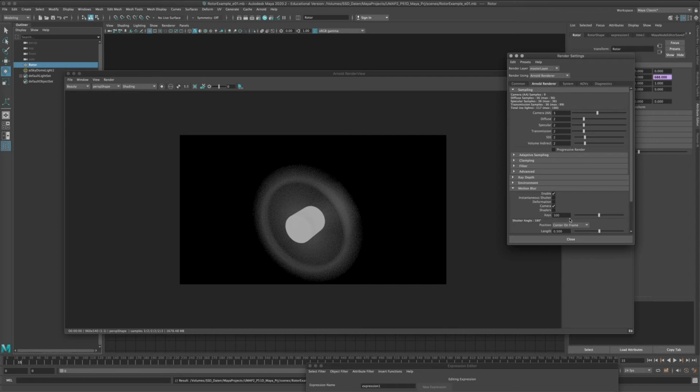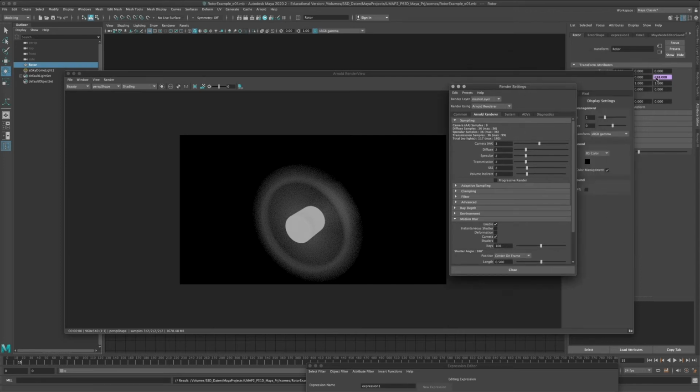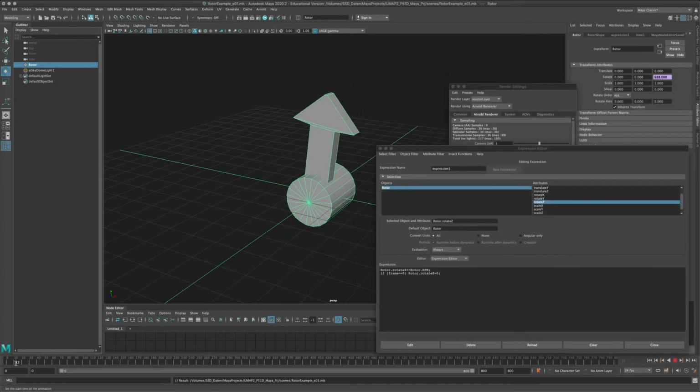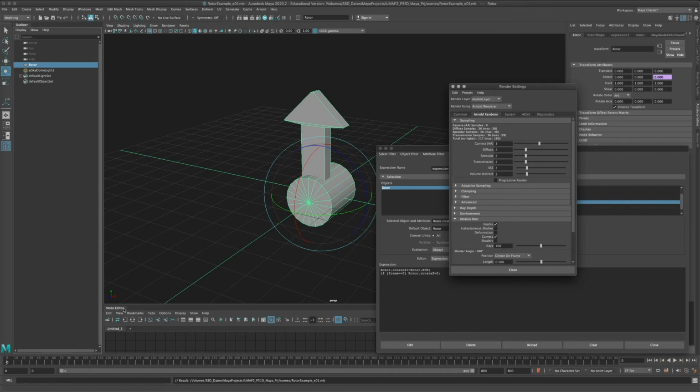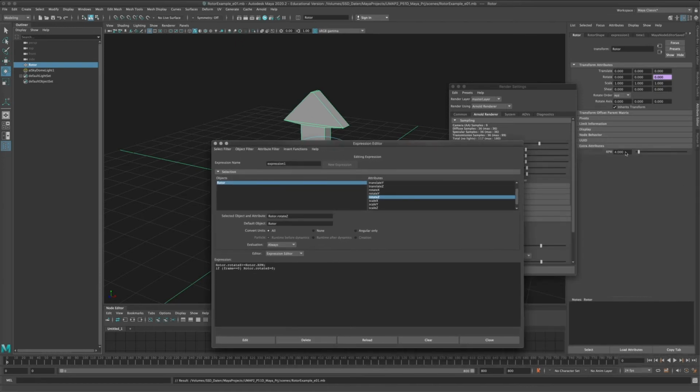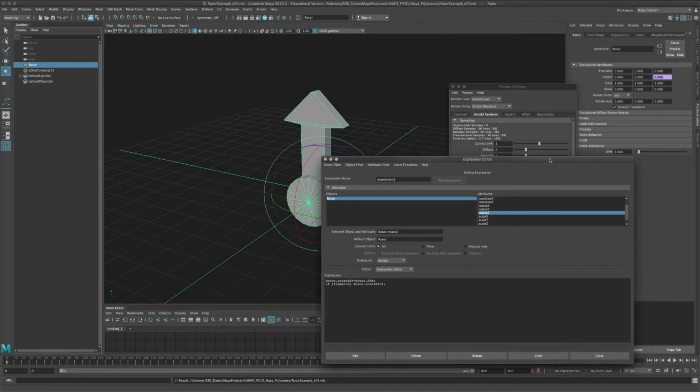And that's a really big problem, because this runtime expression is currently evaluated every time step. As long as I step through the frames in Maya's timeline, and it's just going to do frame 1, frame 2, frame 3, that's not going to be a problem. But Arnold, when rendering, tells Maya to evaluate 100 time steps between frame 0 and frame 1. So this expression is going to add 100 times, actually 102 times, between frame 0 and 1, and my propeller turns way faster than I intended.